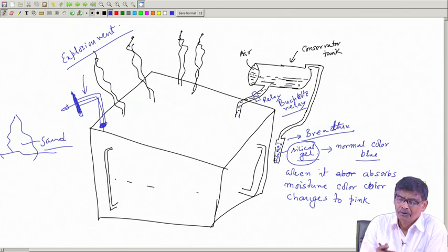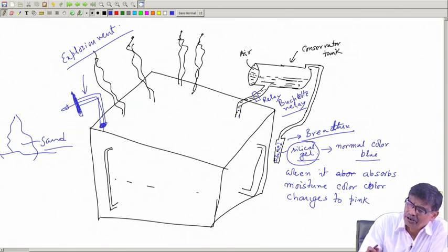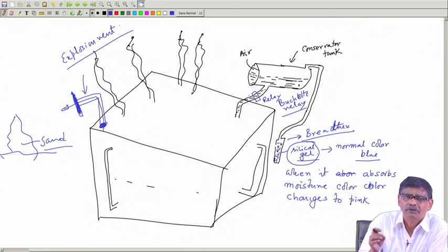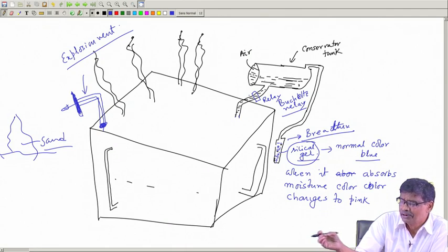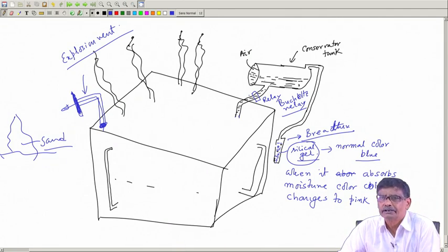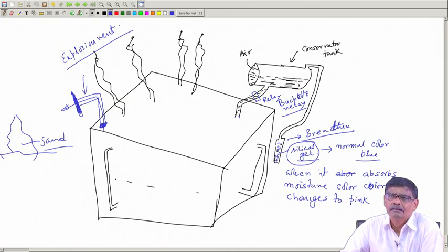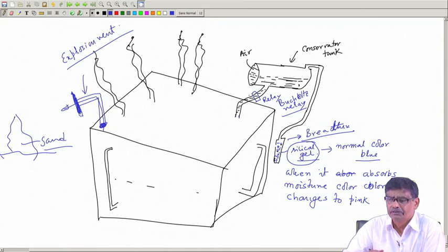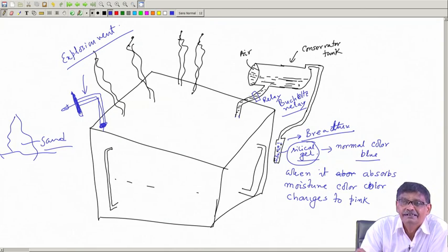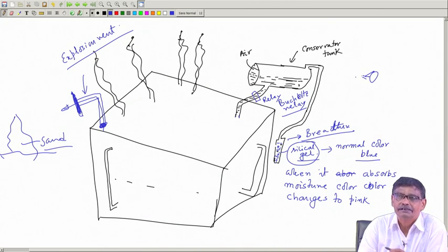Okay. When oil is heated, oil will push out, density will fall, there will be some floats inside, they will move. Through that mechanism, you can initiate some operation or it can give you some alarm, so that things are not good for the transformer. Oil is almost vaporized here. You know, a float like your toilet float in this one.